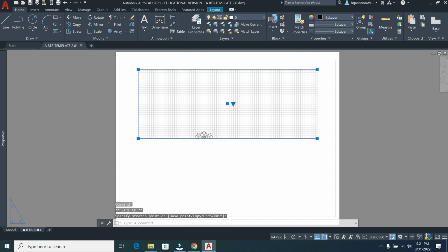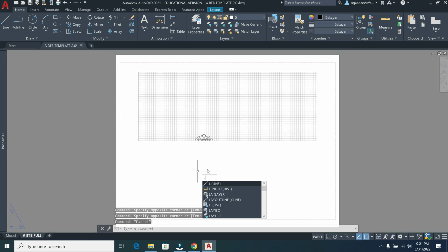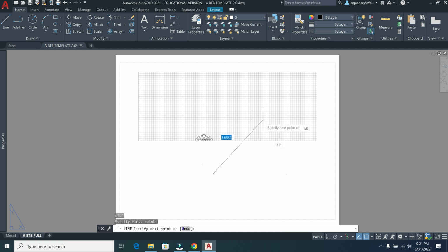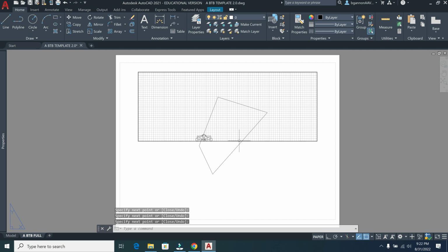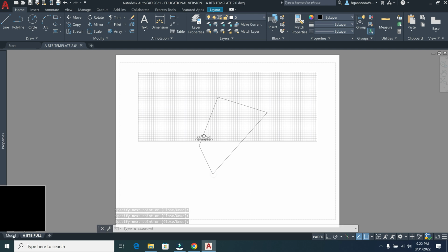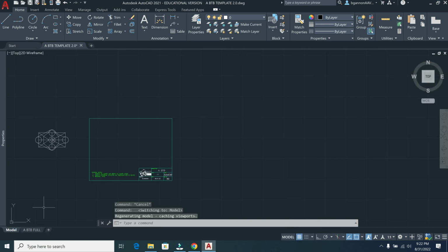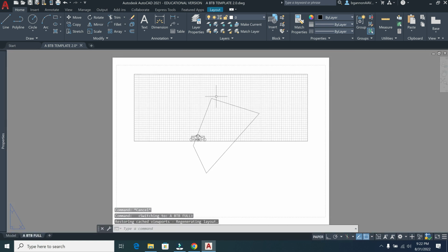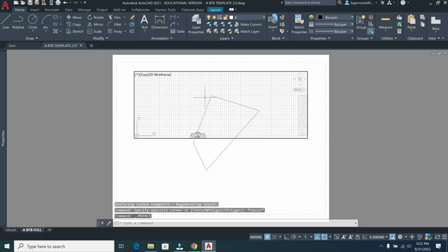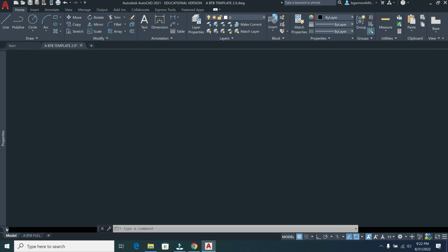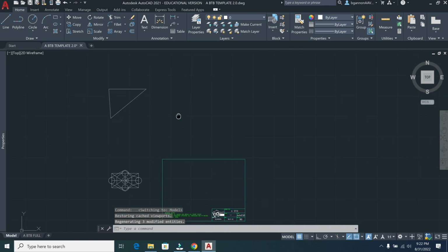Now if I wanted to start drawing some lines on here, for example, if I just used the same tools here, line, and started drawing all the way across this, you can see I have this line. Now this does not show up back in our model space. If I go back over here to my model space, none of that shows up. Now, if I was to double click on this and draw inside of that viewport, this would show up on my model space, which we're actually going to do for a part of this activity in a moment. But you can see it back here on this model space up here in the upper left. But I'm going to go ahead and delete that.